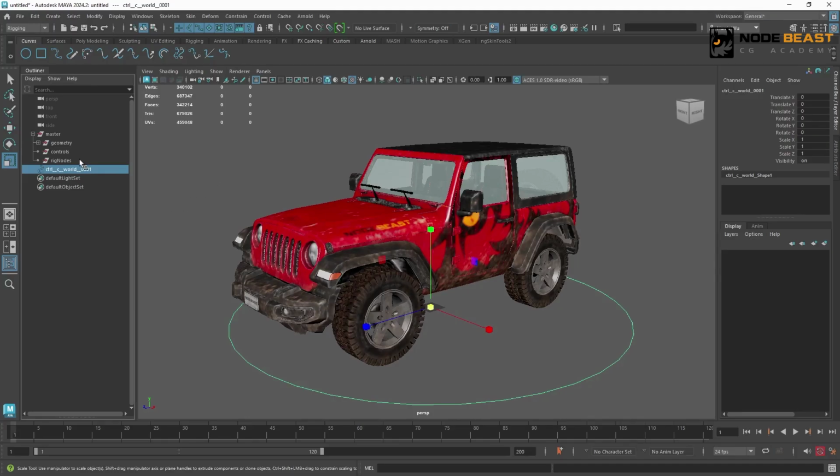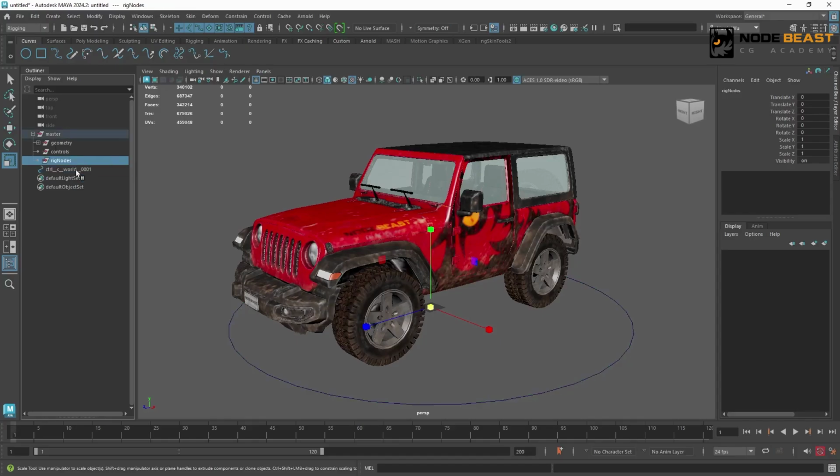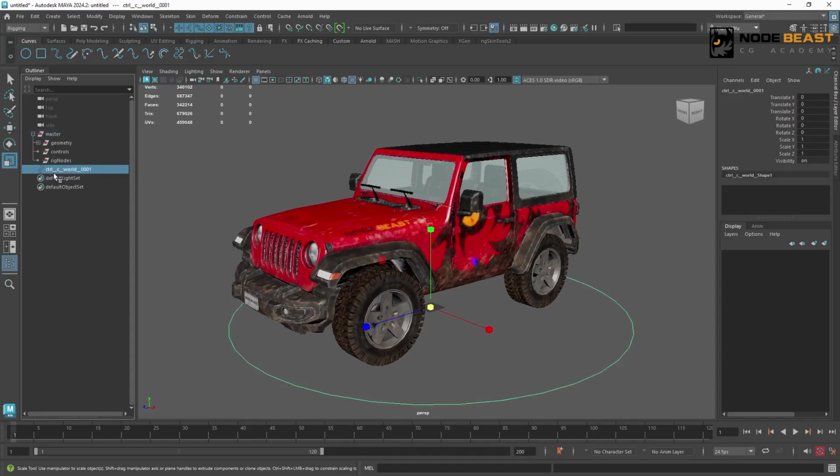When we write it, we will search for the world controller in this rig. This world controller, its name is Control-C World 0001. Now if I have another rig, and because I wanted to differentiate from others, I called it, for example, Control-C World Tom 0001. Well, the tool I just wrote will no longer apply. I would need to keep adjusting this script. This is clearly unnecessary, so we need to be careful here.